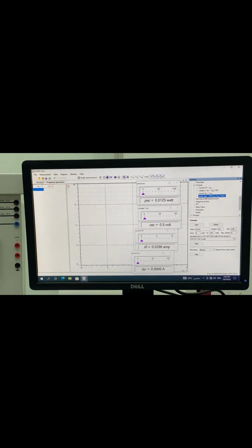Now before we were measuring one voltage, one current and two voltage. Now in the short circuit test we are measuring one voltage and two currents. Why? Because now we need primary current and secondary current both. So we are turning this on. Make sure this is 0. Turning on, and we have to apply the voltage very slowly.